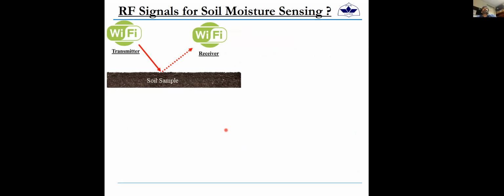All right. So as I have motivated why we are going to put our transmitter and receiver in this fashion, now let's proceed. There will be only two or three mathematical equations, but they are necessary. We cannot avoid them, but let's try to understand them. So reflection coefficient, this symbol, if you don't know, is called capital gamma. Capital gamma here is equal to a numerator divided by a denominator. So you have eta2 minus eta1. This symbol is pronounced as eta.